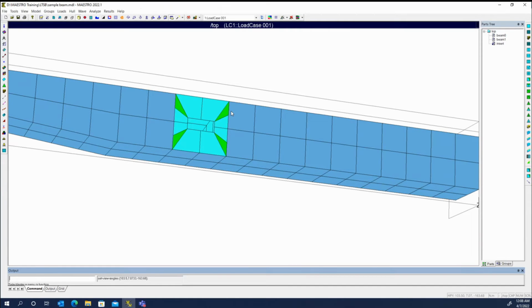Because the elements belong to different modules, so do the nodes that are used to create them. They happen to be in the same physical space, so they're within the nodal join tolerance, so they'll get the same FE tag and be treated as a single point. But for editing purposes, they're in different modules, so they're going to be different nodes.